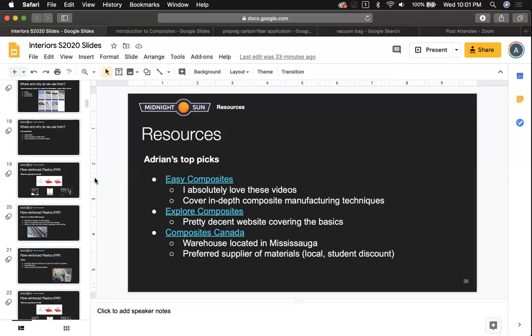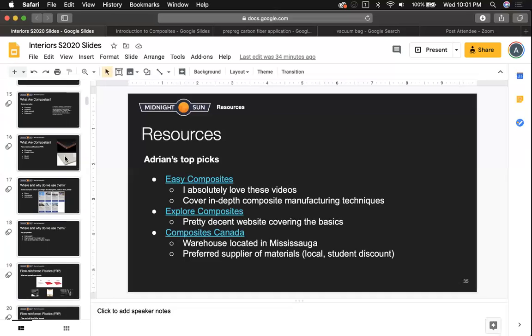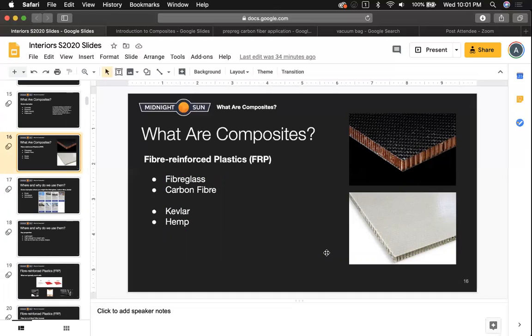Surprisingly, the actual properties between fiberglass and carbon fiber are relatively similar. Carbon fiber, although it's quite hyped up and something we all like to see in expensive products, is relatively similar. The only difference is that carbon fiber tends to be stiffer for its own weight, so it's a higher stiffness to weight ratio and potentially a higher ultimate strength. But overall, there isn't a major difference aside from the look you get and the slight weight reduction. And carbon fiber tends to be moderately more expensive than fiberglass. So depending on the application, it's totally reasonable to switch to fiberglass as opposed to carbon fiber.